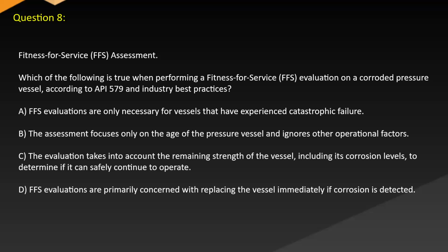FFS. Assessment. Which of the following is true when performing a fitness for service FFS evaluation on a corroded pressure vessel, according to API 579 and industry best practices? A. FFS evaluations are only necessary for vessels that have experienced catastrophic failure. B. The assessment focuses only on the age of the pressure vessel and ignores other operational factors. C. The evaluation takes into account the remaining strength of the vessel, including its corrosion levels, to determine if it can safely continue to operate.